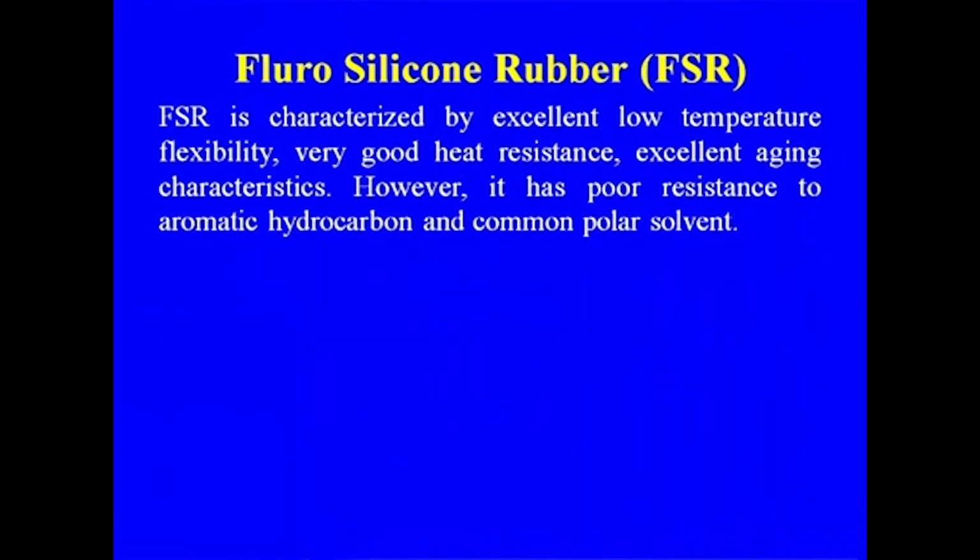Fluorosilicone rubber, this is another specialized rubber, characterized by its excellent low temperature flexibility, very good heat resistance, excellent aging characteristics. However, it has poor resistance to aromatic hydrocarbons and common polar solvents. So, this is another class of the synthetic rubber.